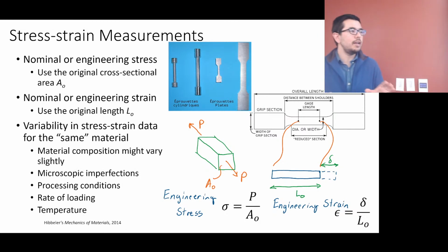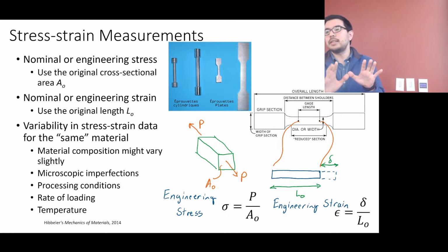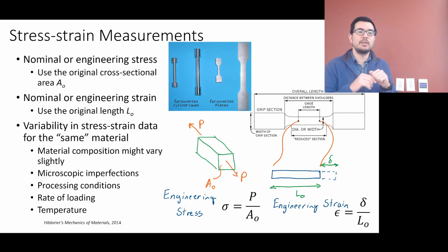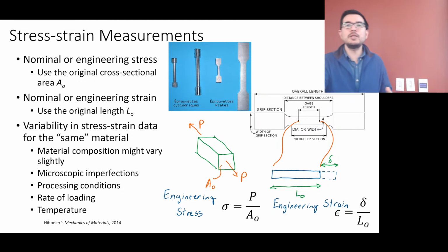You try hard to set up these experiments, and be very careful with the instrumentation, have a great load cell, have a great extensometer. What does that mean? What does great mean? Well, it means that the level of noise you have is low compared to the minimum amount that you're going to measure, right? So someone says, hey, I've got a 5 kilonewton load cell. Do you want to use it? And you're like, my sample is really small. Small cross-sectional area, has a low elastic modulus. I only need 100 newtons of force, max.